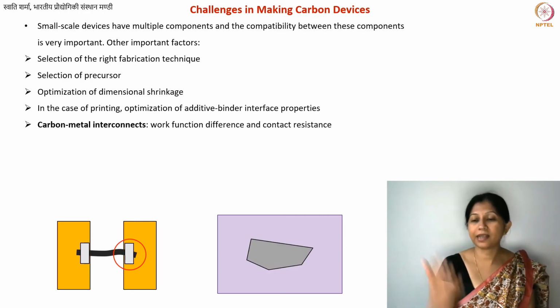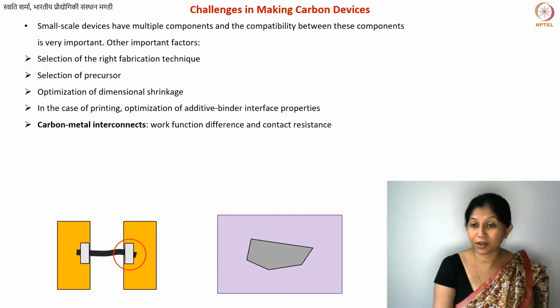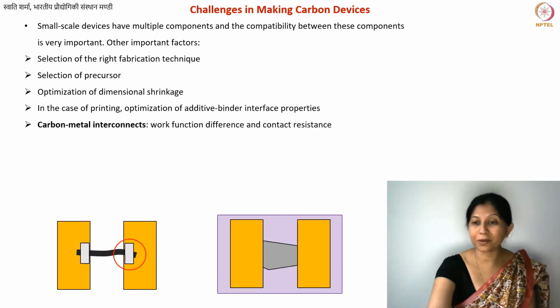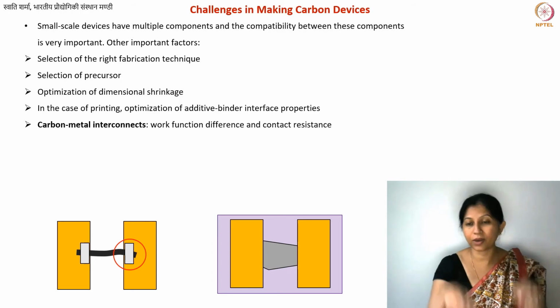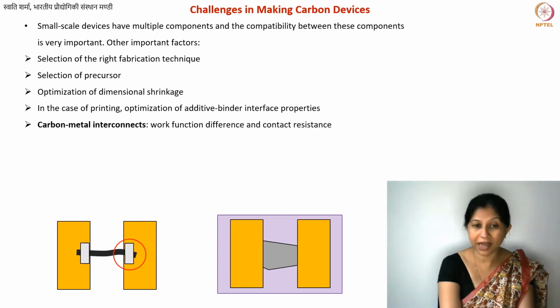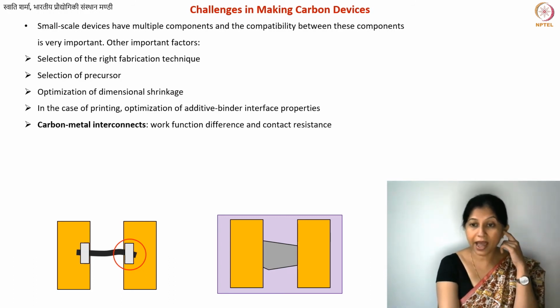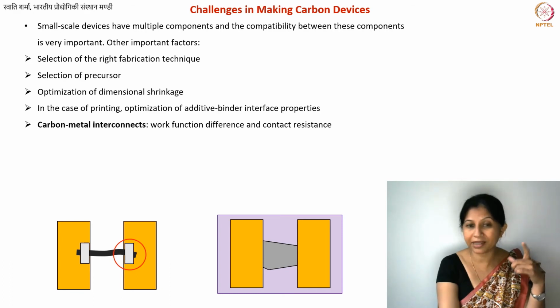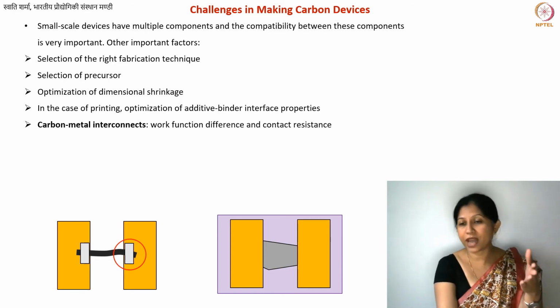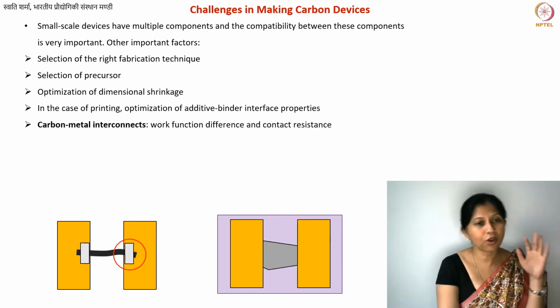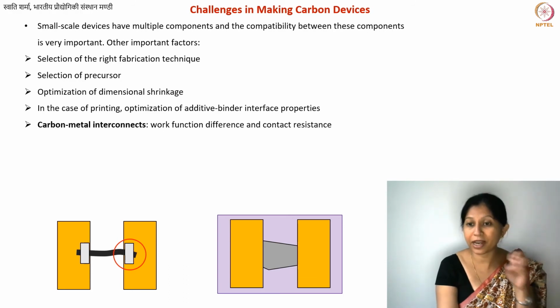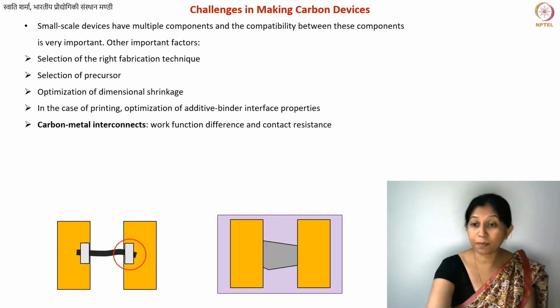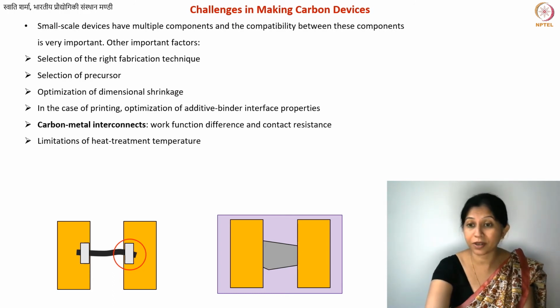Let's say you have a graphene flake on top of silicon oxide, and now what you can do is, from on top of that, sputter your metal contact pads. But in this case, you will see I have made much larger contact pads compared to what we had in the case of carbon nanotubes. So you may have to play with these fabrication parameters a little in order to get your optimum performance from your device, and reproducible.